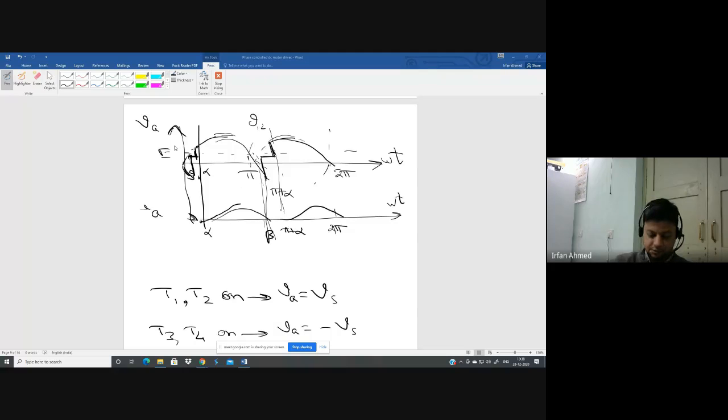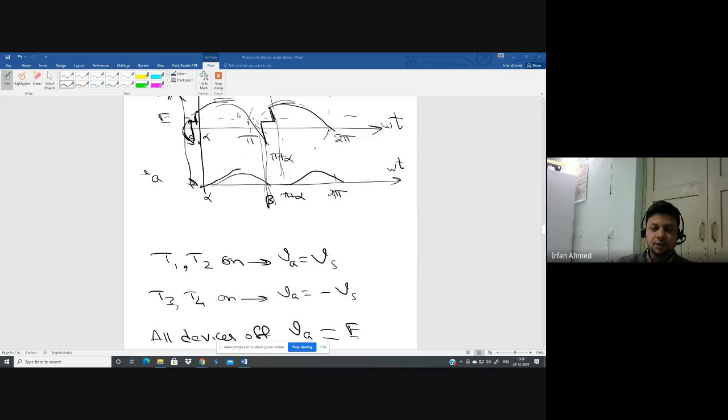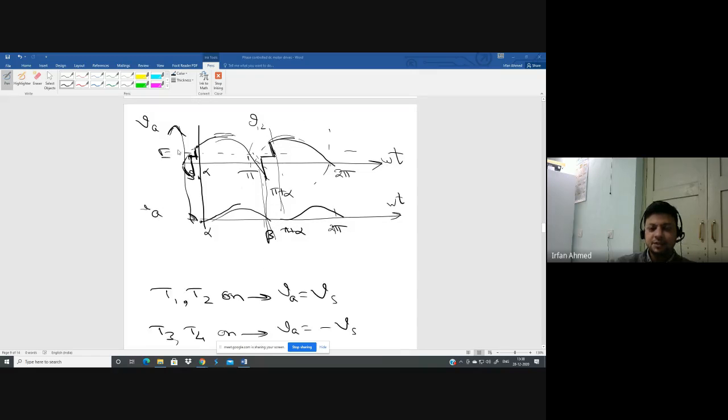As you can see, the armature voltage, I think this also we had discussed, is not perfect DC. It has a DC component as well as a number of harmonics. And as I told you in the previous class, the harmonics can be filtered out, so that what passes to the load is the DC component only. How much is the DC component in this armature voltage?